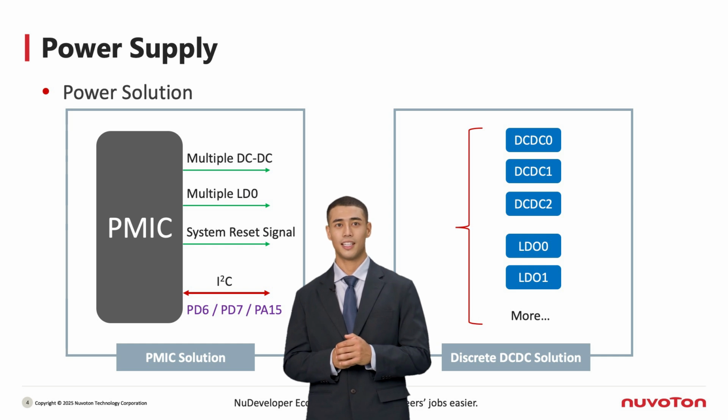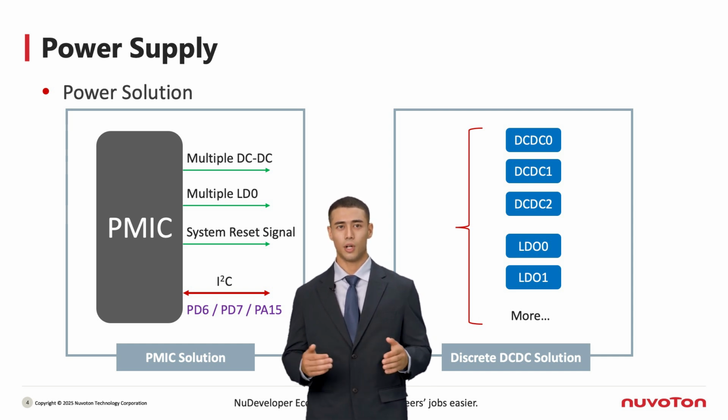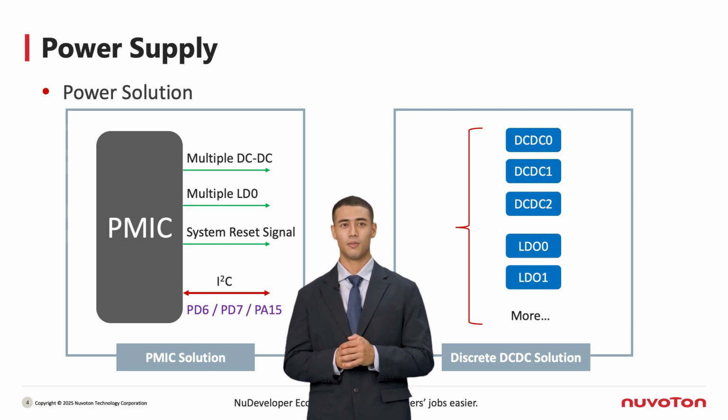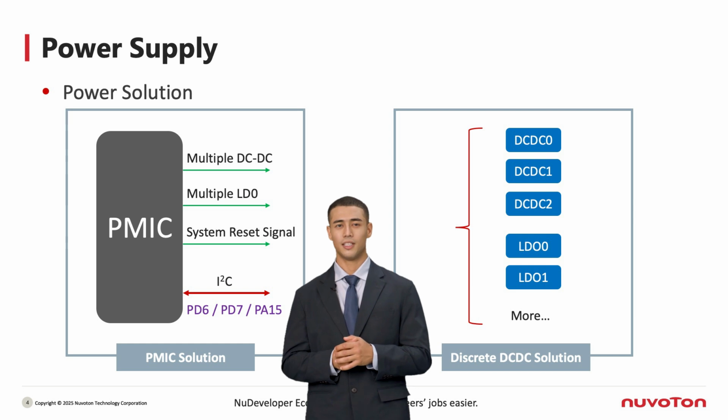For a discrete DC-DC solution, the power rails must be matched to the consumption of each supply, and the DC-DC and LDO components selected accordingly. In addition, the MA35 power-up sequence requires strict adherence. The IoT development board schematic should be referenced during circuit design to ensure compliance.